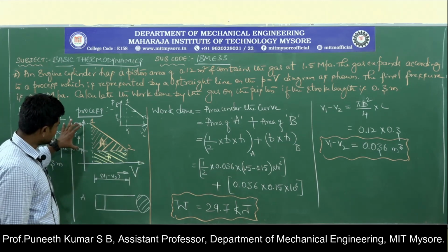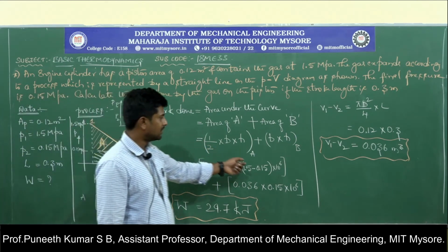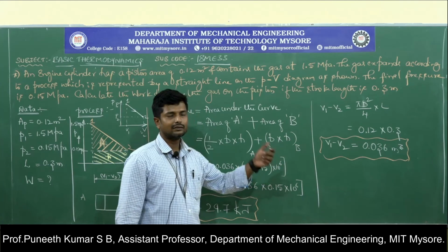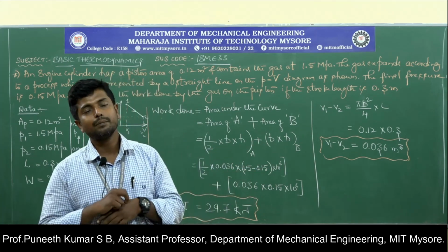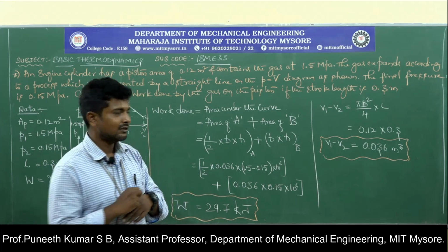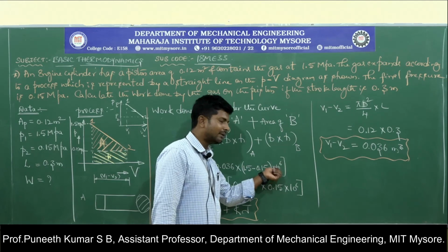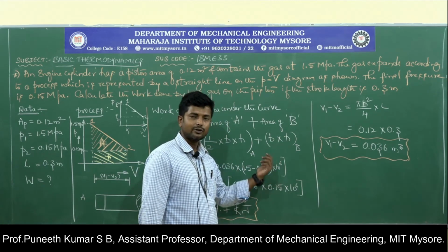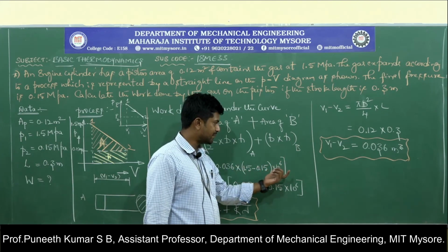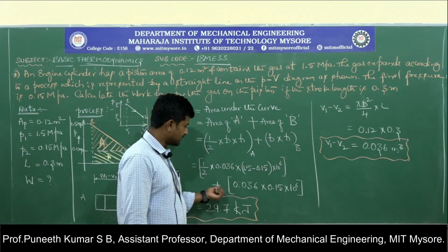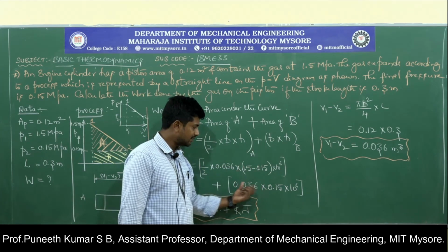While taking the difference of initial and final pressure, we need to be very careful. As it is given in megapascal, it is our responsibility to place it in terms of pascal. To convert it, we have multiplied it by 10 to the power of 6, so it comes out in pascal. So all the units are in basic units. Next, we have added the rectangle.